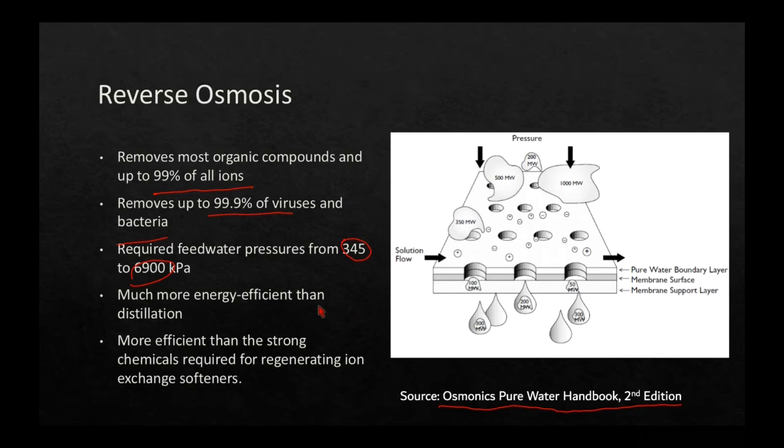Now, why would we want to use this instead of distillation? It uses less energy. Why would we want to use this over demineralization? Well, we don't require all those nasty chemicals, so we don't need sodium hydroxide or hydrochloric acid for regeneration. We don't have to worry about disposing of these strong acids or strong bases used with regeneration.